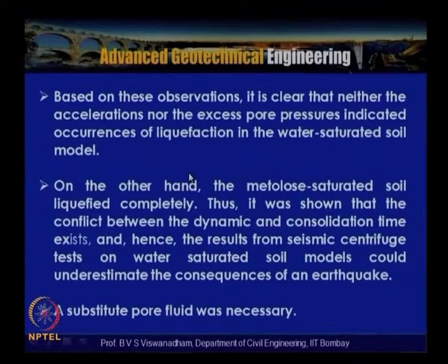Based on the observations, it is clear that neither the accelerations nor the excess pore water pressures indicate the occurrence of liquefaction in the water saturated soil model, because the excess pore water pressure has not reached the level at which liquefaction can occur.